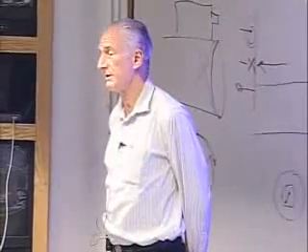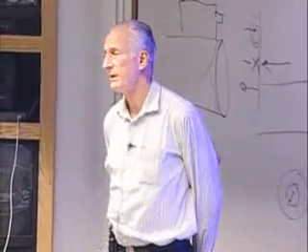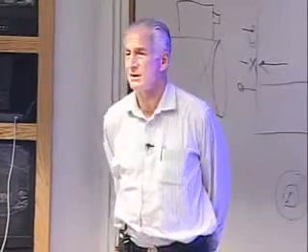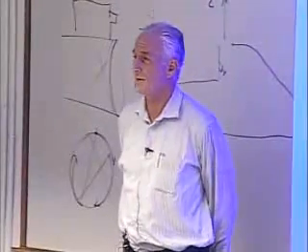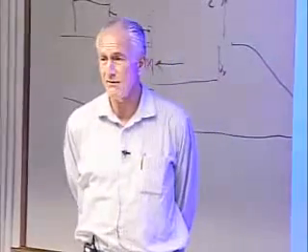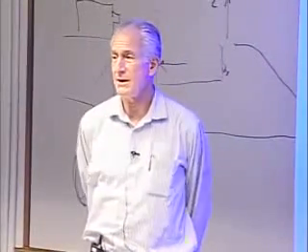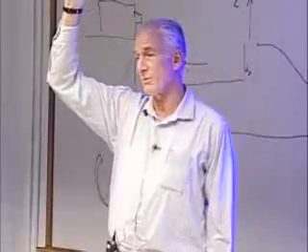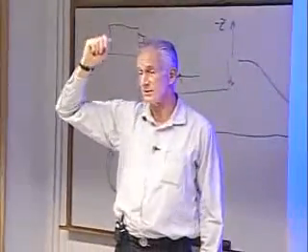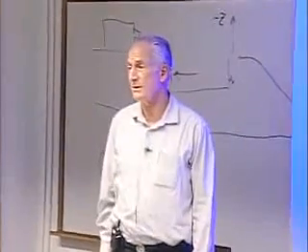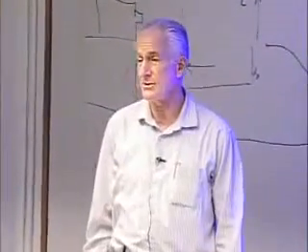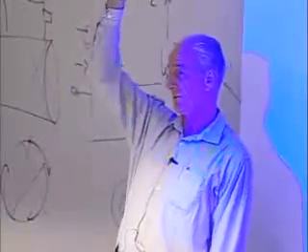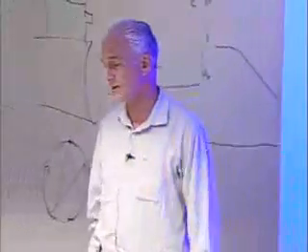3Gs is not particularly comfortable, but on the other hand, any healthy person can tolerate 3Gs for a minute or two. So it's not a real big deal. There have been concerns if the pilots have to reach some of the overhead switches to reconfigure the OMS or the RCS at 3Gs, could they actually reach it? And some of the shorter pilots decided that with the Gs they probably couldn't, and so they actually